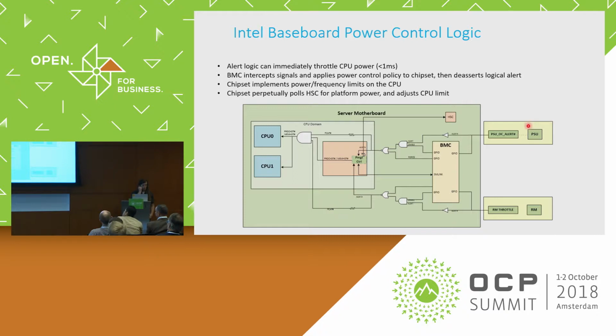So we had those three individual single-phase power supplies. We could lose one. If we lost a second one, then we'd have to reduce power. So we configured the PSU firmware on a power overcurrent event to drive out an alert, and in our baseboard management controller, we have control of these gates that will allow that alert to propagate through and result in the power capping event.